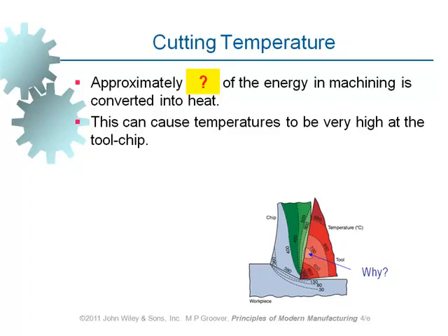Number 3, safety. If you lower the temperature as much as you can, you are not putting the machinists or people around the machine in danger. There is a safety hazard when the temperature of the machining operation is really high because of the chips which are falling off, and someone could touch those chips, and that happens in the workshop very often.